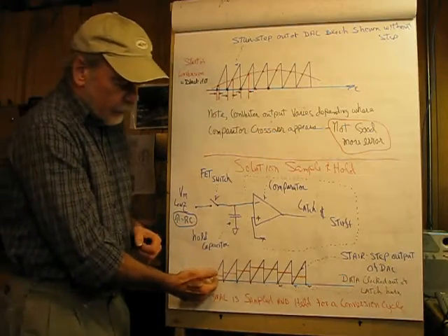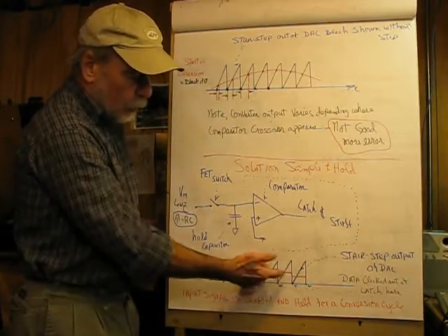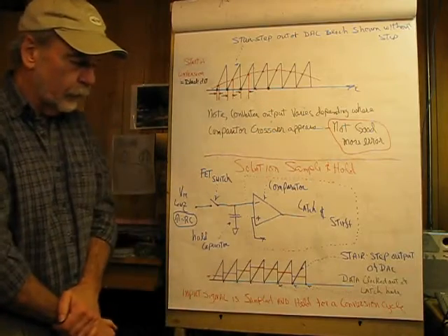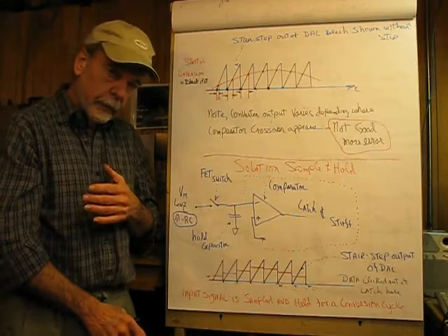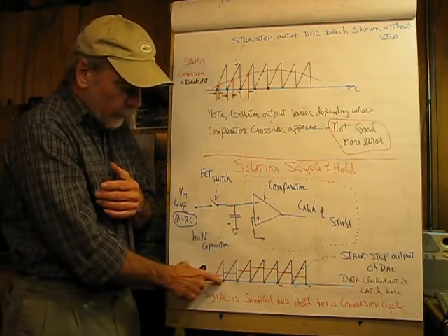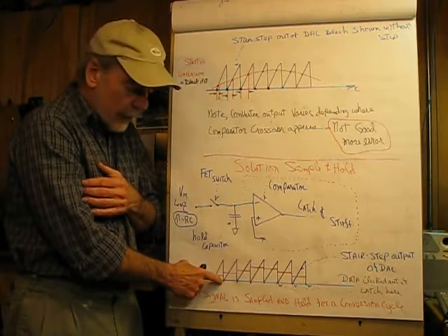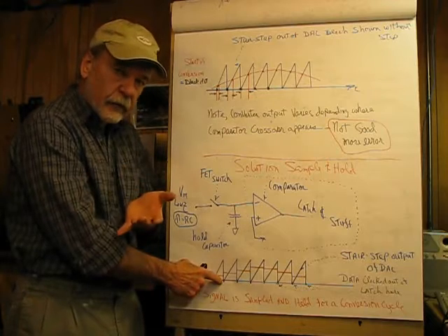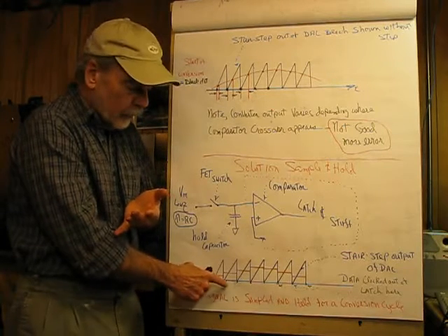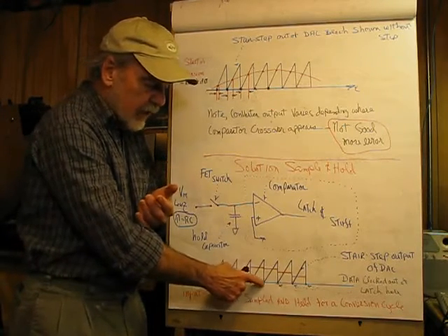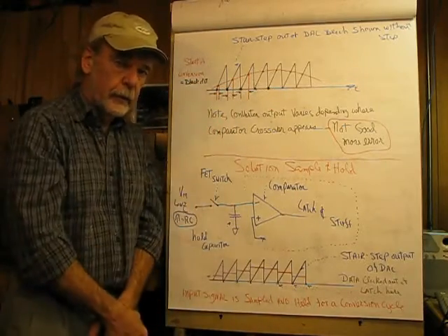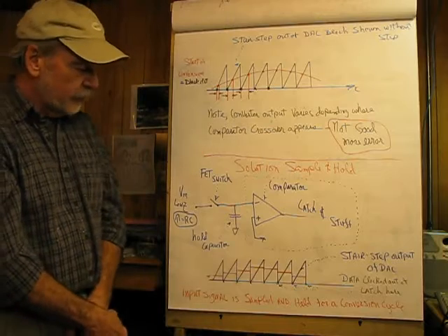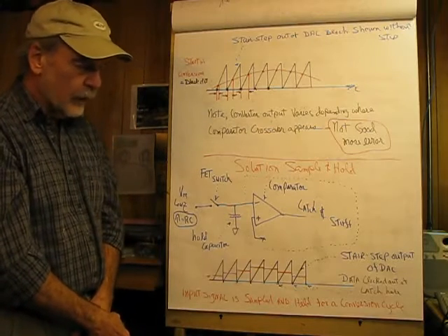So as you can kind of see here, by the sample and hold, at least we're able to reduce the time skew. And also important is the output of our stair-step generator now occurs at the end of a conversion cycle. So we have common times here, and that eliminates this issue that we have up here. So by using S&H, we've made some progress.